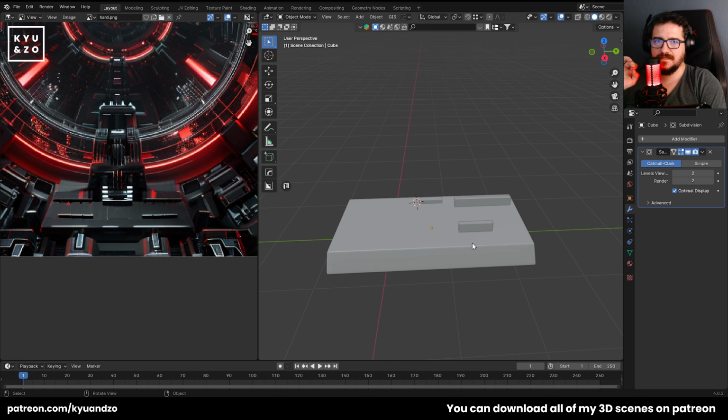It's the same situation again, but be careful that if you select similar normal, it's gonna choose these ones too. So Control Shift right mouse, this is standard, don't worry. Control Shift right mouse, you can deselect that and you can keep extruding it like this. It's enough to bring it here because we're gonna mirror and everything will be fine. And of course, we just need to have one more edge loop here.